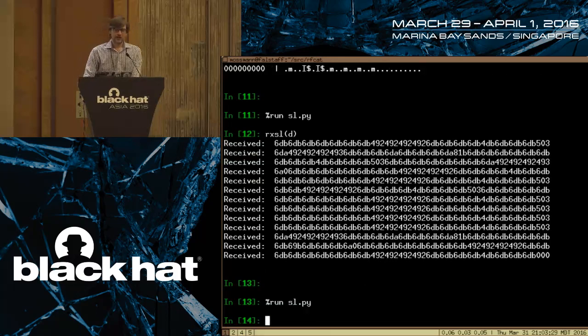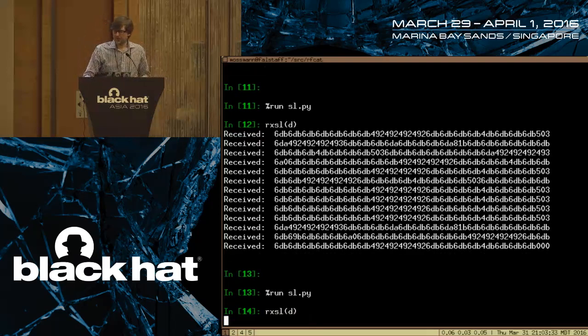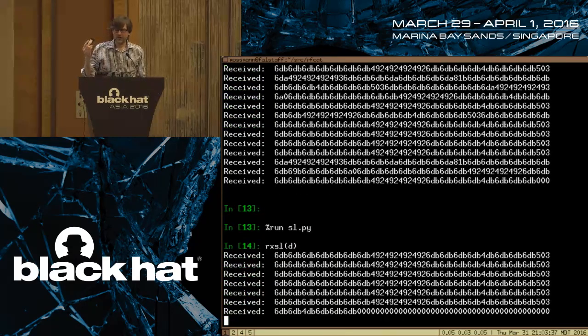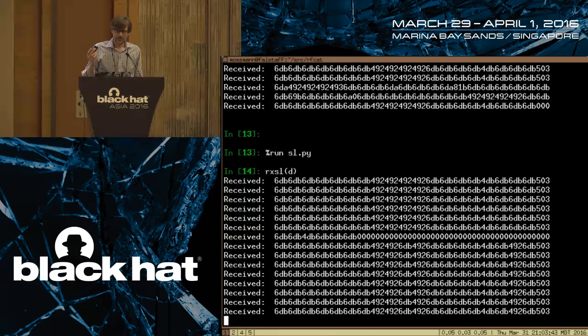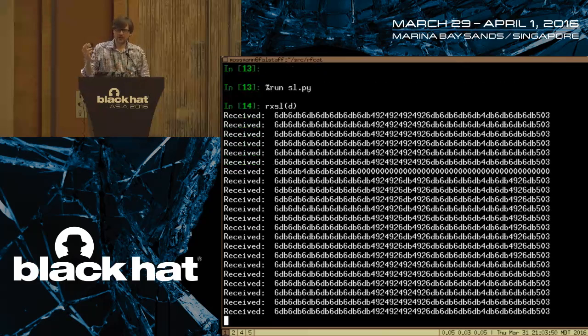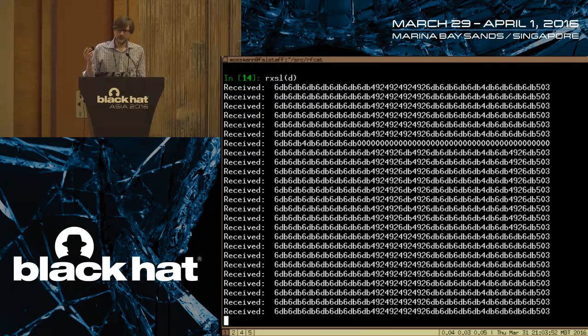And then I go back over and rerun or load that updated code in, and now you see I'm receiving fewer. I actually got one false positive somehow. Not sure how that happened. But here, when I make it transmit, let me try it again. You'll see that it's very consistent. It gets a bunch of packets in a row that are all the same. So that's just a little sanity check that I added in.